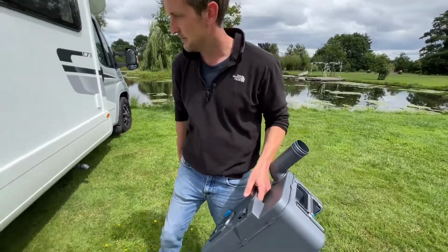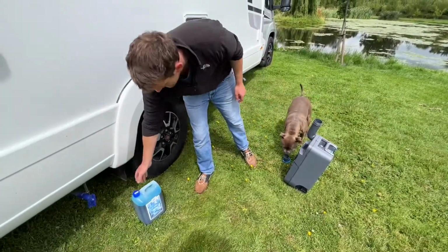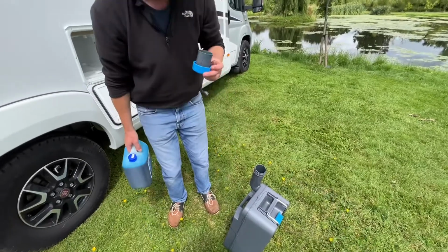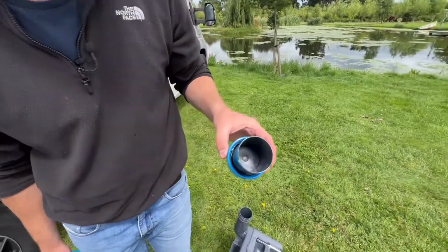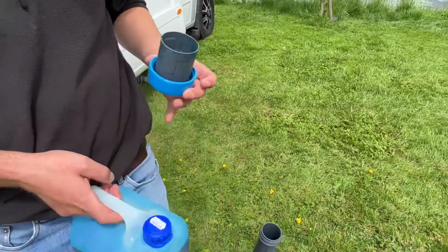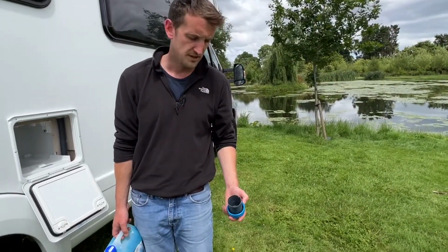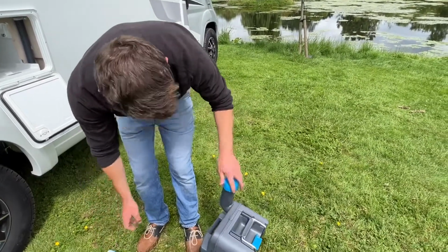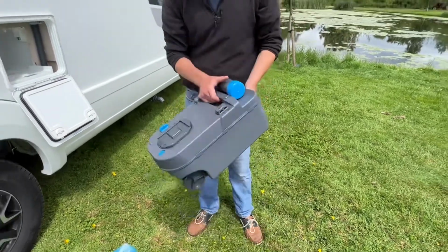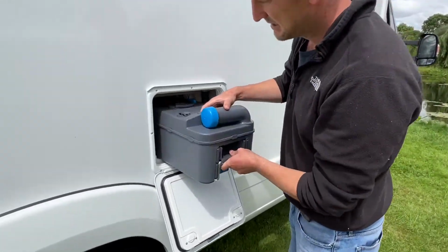And then when you get back to your motorhome, there will be some chemical which you'll find in the garage compartment that will look like this. And then with the cap, you will need the 60mm measurement. Now inside the cap there are measurements. The 60mm is just down there, so put 60mm in there, put the cap back and pour it back in, and then put about half a pint of water in there as well. Swirl that around, that will fold back in like that.